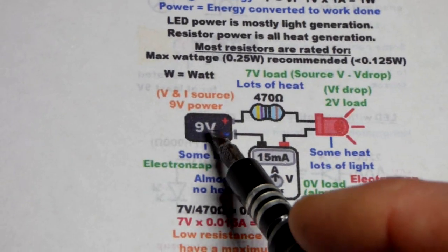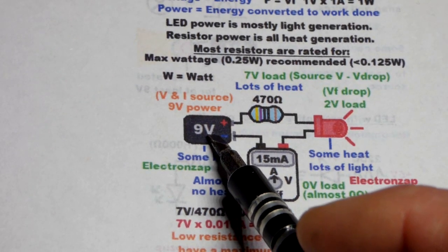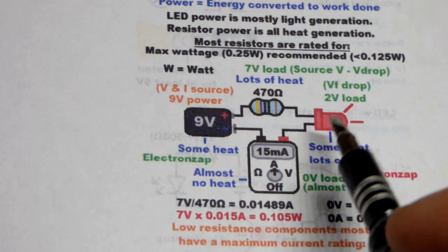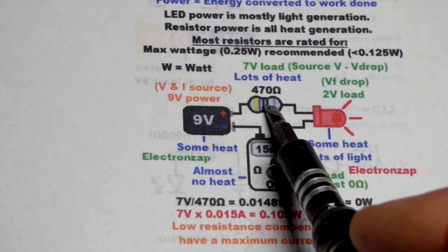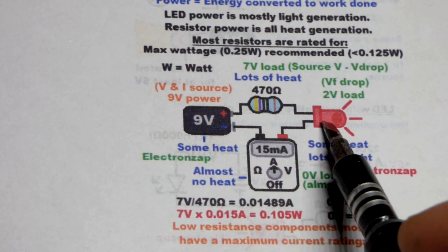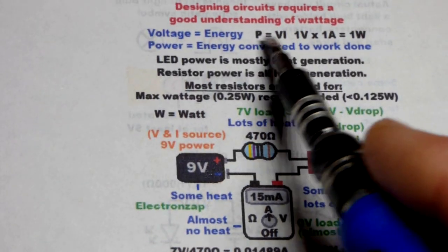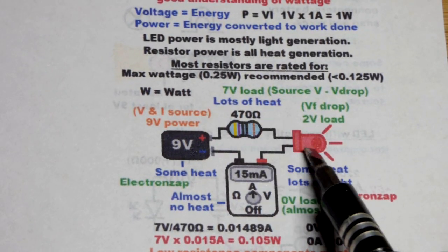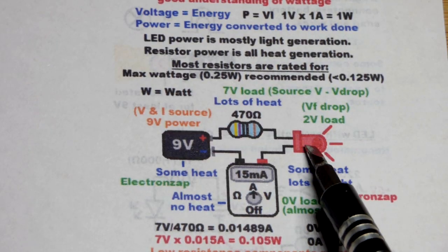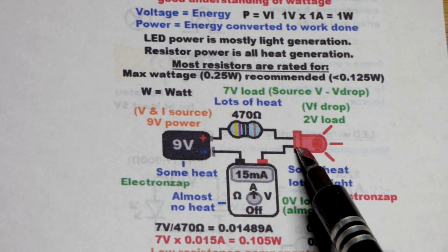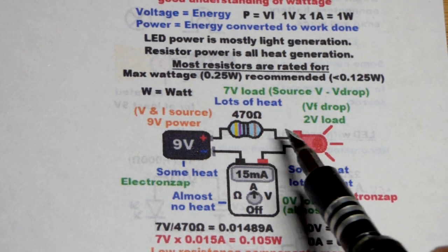You don't have to do that a lot. It's just when you're working with a voltage that you're not used to, and then maybe a load, you're not used to how much current the load needs, and you've got a resistor setting that current. That's when you do this math. You make sure that whatever resistor you use, the current's not going to damage the, in this case, LED right there. So we want to stay below 20 milliamps, so 470 does that.